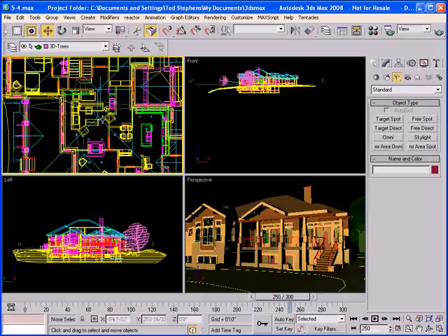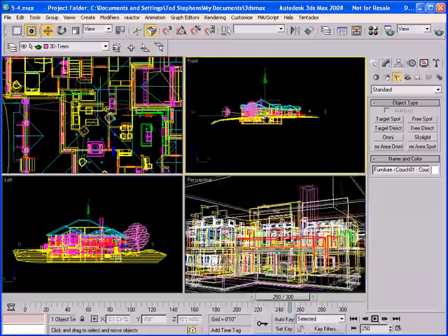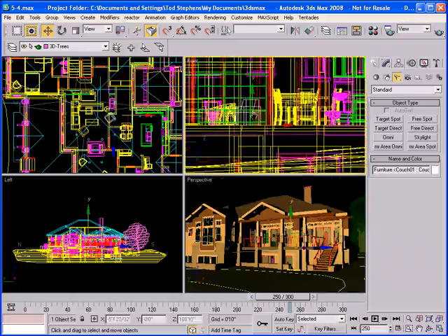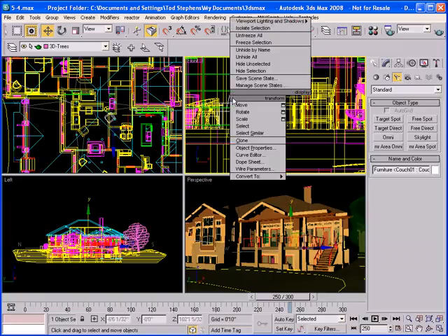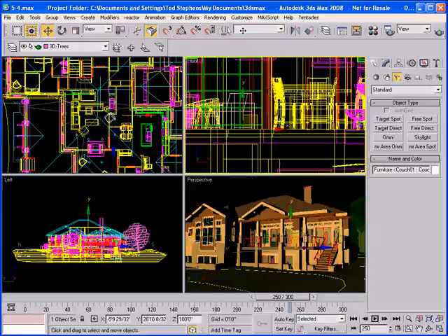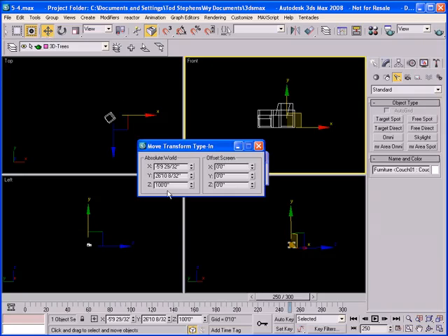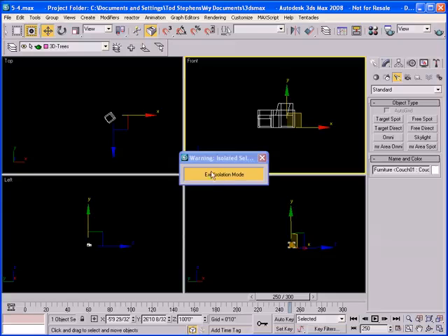So I'm going to click on one of the pieces of furniture in here. It's just a chair. What I want is a reference point basically of the top of the floor of that particular room so that I can add a light in there and it'll just be easier to move the light around. So that chair, I'm going to zoom into it. A little tough to see in my front view. So I'm going to right click over the chair and turn on Isolate Selection. And what that'll do is just hide everything else except the chair. So notice that XY gizmo there in the front view. The bottom of that gizmo is at the bottom of the chair. That's what I want to make the 0 Z height or reference. So if I right click over the Move command, I can see the Z height is at 100 feet right now. So I want the bottom of that chair to be at 0 elevation basically.